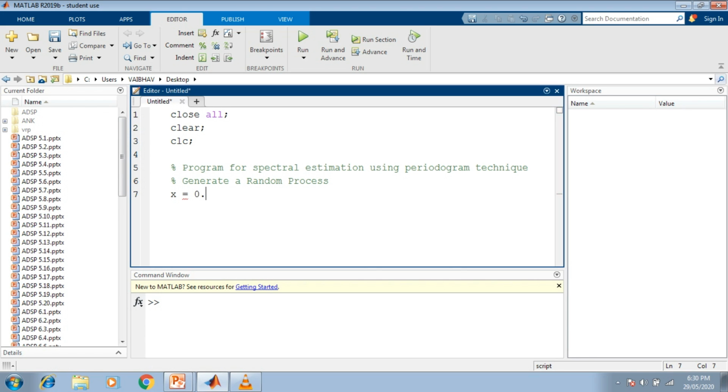If we take the amplitude to be, for example, 0.5, multiplied by the cosine function, and within the parenthesis we show 0 to 99, so a total of 100 samples on the discrete time axis, multiplied by the constant pi divided by 16, for example. So this will simply denote a discrete time signal here.